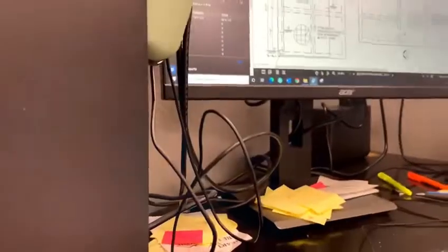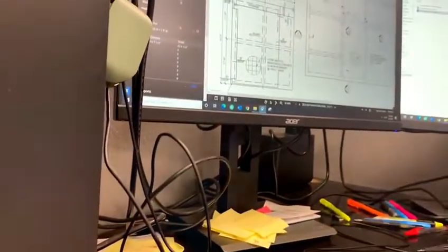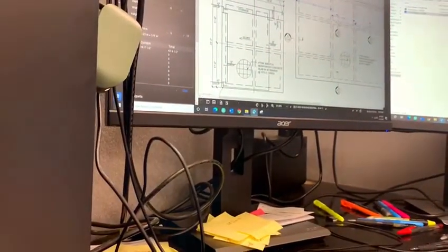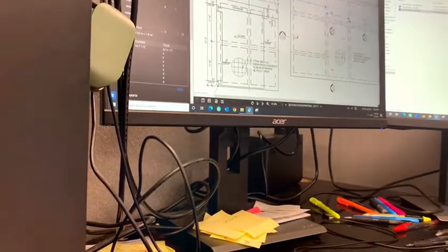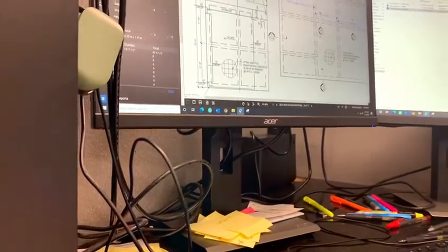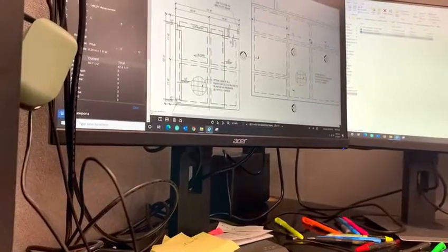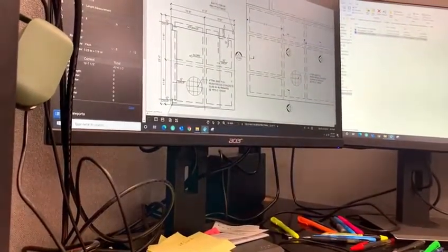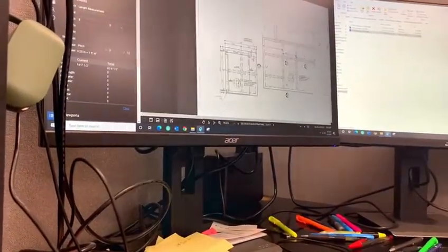So then I'll add a grade beam in an obscure spot, which means if we have a wall going through here and the designer put a grade beam right there, I have to delete that and move it there. So sometimes it could be jagged. And if that seems weird, then we have to move all of our grade beams down. Well, let's open the floor plan of the house.